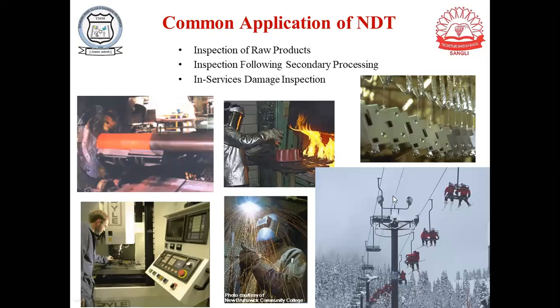These wire ropes. Suppose you have any doubt that there may be some problem, or there may be some tension, or some defect in the wires. You cannot just tell all your customers to get down from this car because we need to check the rope for any defect. Next time no customer will come to you to sit in the car. So what you can do is check these ropes when it is in application only. If there is any damage in the rope, or even if there is no damage but you still feel you should check just for precaution, you can check that by a non-destructive test.